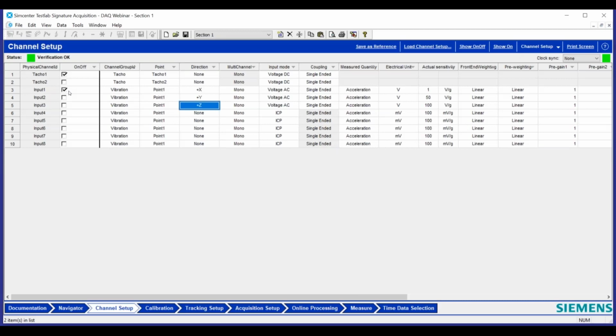And actually, I don't really have a test object. So what I'm doing is I have a recording of the RPM signal and the response from my accelerometer, recorded on my computer, and I'm playing it out through the headphone jack into those 2 channels, the tacho channel as well as dynamic channel input 1. But actually into a SCADAS as well. Yeah. Is that right? Yeah. Okay. Yeah, so you have it into the SCADAS Mobile. Okay. Yeah. And I have a picture of it. We'll take a look at it later.